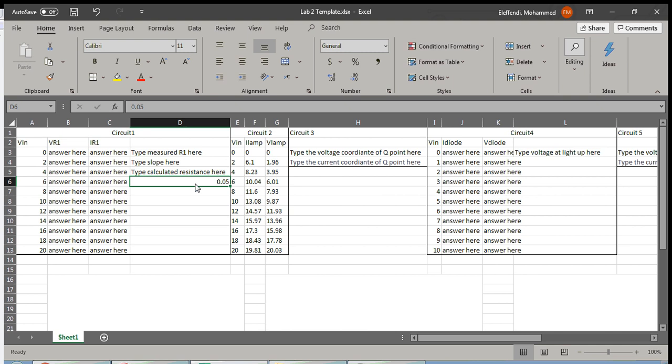Now, if you are doing this in person, you will definitely get something here for the percent error. If you are doing it online, then you could probably get 0% error. And this is because the Tinkercad does not simulate any measurement errors. So each measurement device, like an ammeter or a voltmeter, will have a certain error in the measurement in real life. So there will be meter bias and thermal noise, and that will affect the accuracy of the measurement. But the simulator does not simulate that.